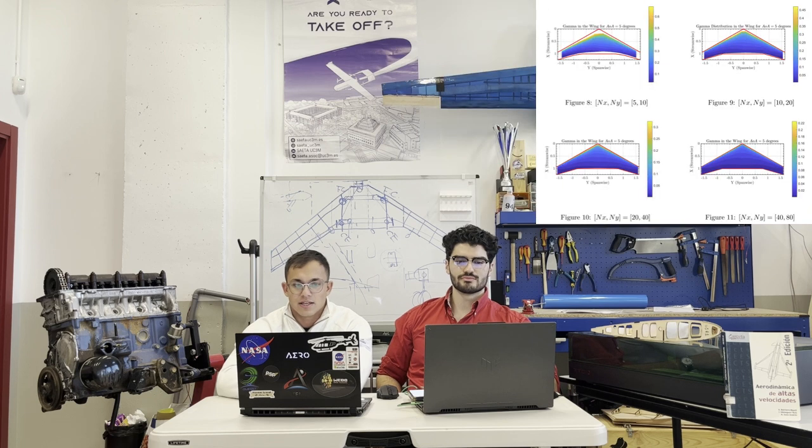While less detailed than the 3D panel method, the vortex lattice method did prove to be more efficient and also excellent for this kind of conceptual design, where you need a rapid estimation of what the aerodynamics of your airplane looks like. Both methods assume inviscid, incompressible flow, meaning they ignore viscous effects such as skin friction or flow separation. This makes them ideal to predict the lift in the linear region of the lift curve, but they also have certain limitations.